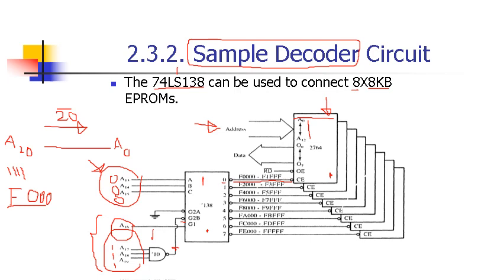If you are talking to the first memory location, you have to provide 13 zeros. So your beginning address would be F, and you take a 0 from these 13 zeros to make the hexadecimal digit 0. So F0000 is your beginning address.